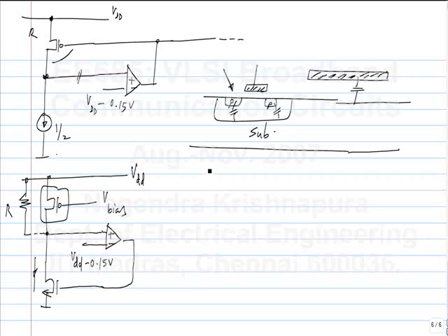So, this is basically what is the current flowing in this. So, let me make this more general, let me call this some Vref by R. So, you have a current that has an inverse dependence on R. That is, if the temperature changes and the R changes, the current will change. Also, if the process changes or the resistivity changes, then the current will change. Okay. So this is a very frequently used type of bias current.